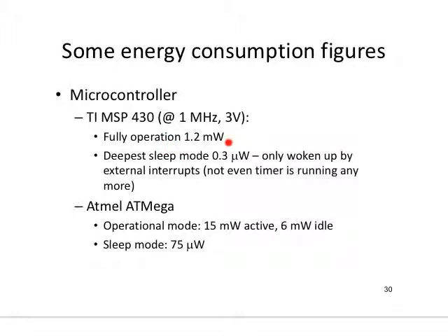Here, just to keep the MSP 430 working in fully operational mode, you have to sustain 1.2 milliwatts, which is more than 10 times the number that we talked about before. The deepest sleep mode, which is the 4th level of sleep, consumes about 0.3 microwatts.